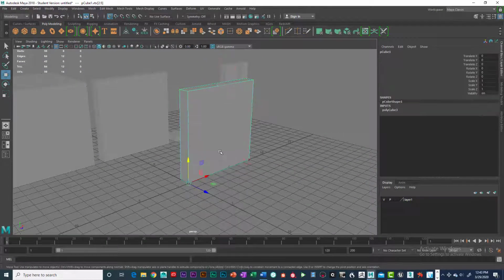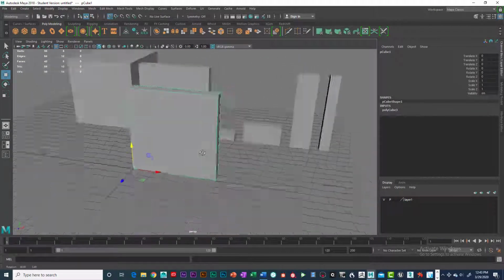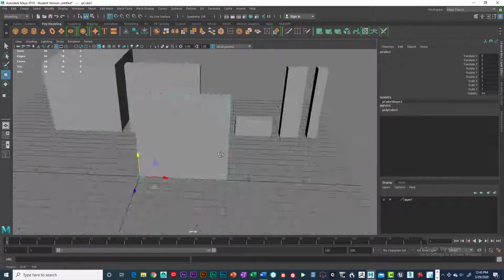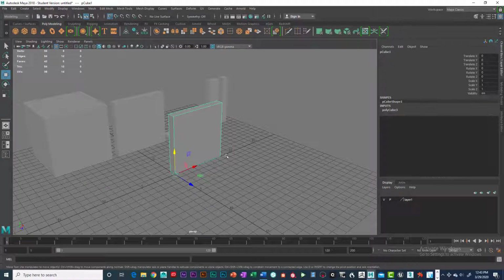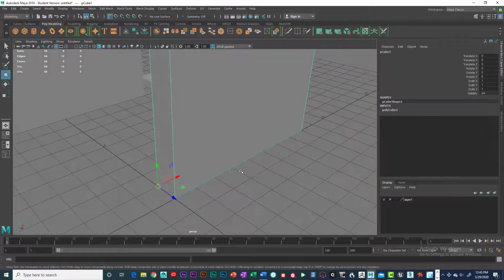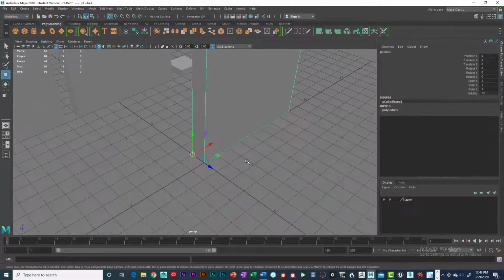So basically I'm kind of following the rule of, it's divisible by 2. Okay. Alright, so you might have your center somewhere like in the center, but to change it we need to make it in the corner. I'll tell you why in just a second here. So I'm going to hold the V key, or the D as in dog, and the V key to snap. So I'm going to snap it to that point right there.